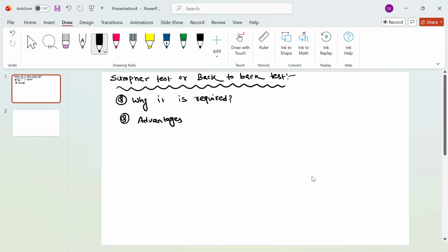In the open circuit test, we consider only the shunt branches from the equivalent circuit point of view of the transformer, and the open circuit test gives information about core loss. With the help of the open circuit test you can calculate the shunt branch parameters, like the magnetizing inductance of the core and the core loss resistance.